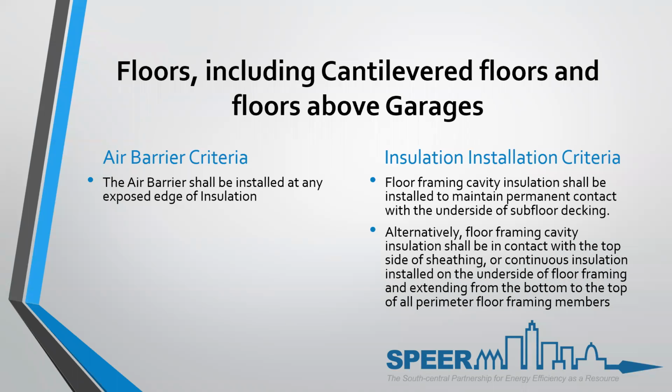Alternatively, floor framing cavity insulation shall be in contact with the top of the siding or continuous insulation installed on the underside of the floor framing and extend from the bottom to the top of all perimeter floor framing members. In other words, if it's fully filled.